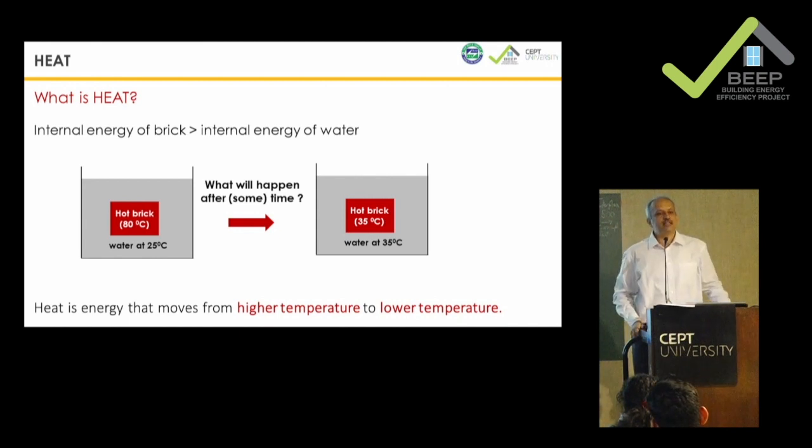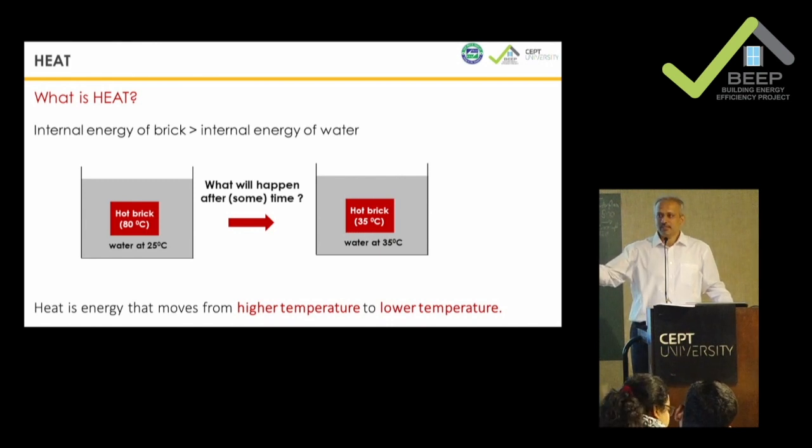So in Jaisalmer, if you don't have any windows in the basement of the Haveli, and the indoor temperature needs to reach the outdoor soil temperature, it will take forever. It will slow down over a period of time, right? What you can achieve in the first 24 hours, in the next 24 hours you might not be able to achieve even half of it, and then it will really slow down. And this is where we need to understand that when we talk about heat transfer, we are not just talking about one way of heat transfer, not just conduction. The moment you open a window, something will flow in.